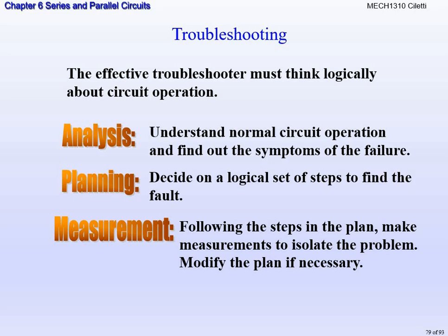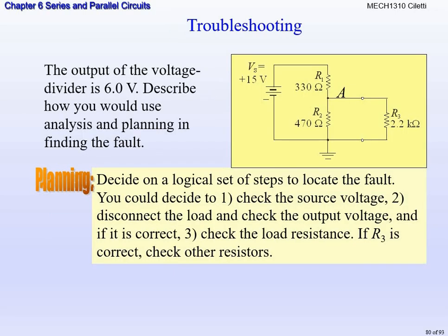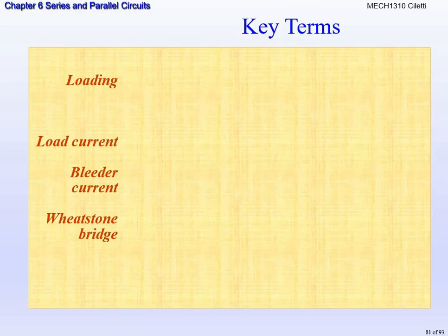They knew it wasn't the motor, but I said, let's isolate it to specific sets of wiring and those sorts of things. Check continuity, check your voltage, check your current, just different sets of steps. That's very, very important. And sometimes it's always good to get someone else's opinion as you're going through something, because you've been racking your brain on this, but someone else might bring a fresh idea.